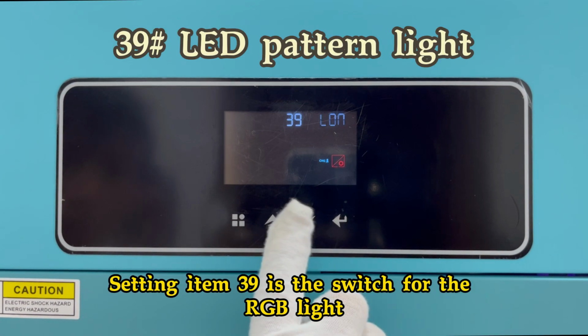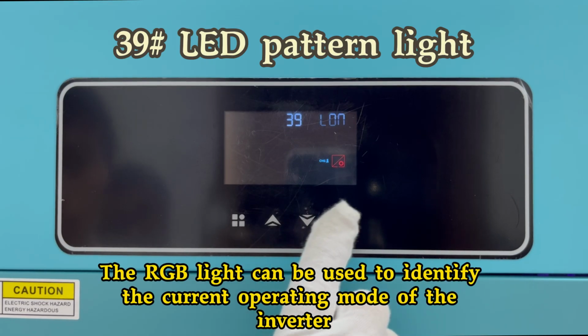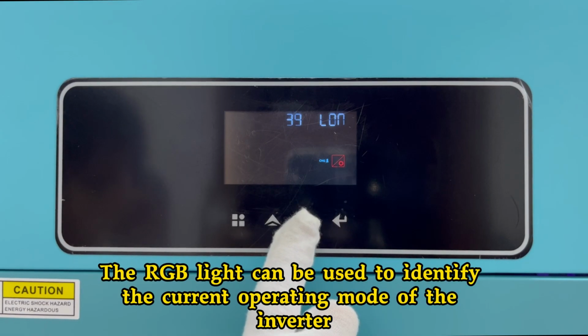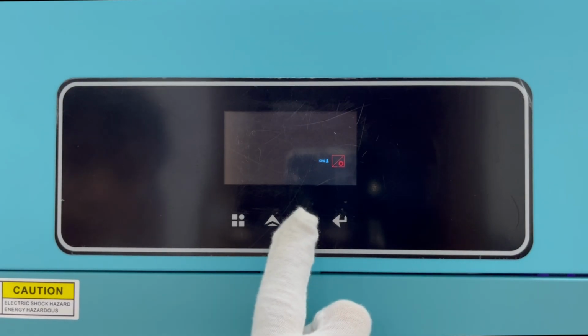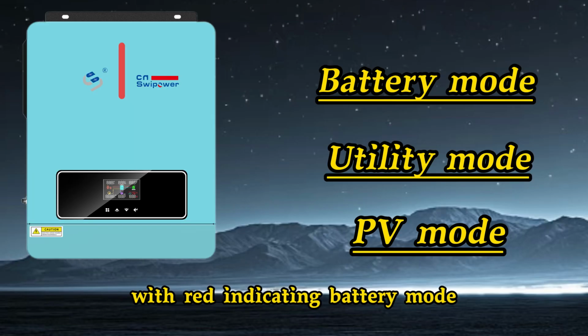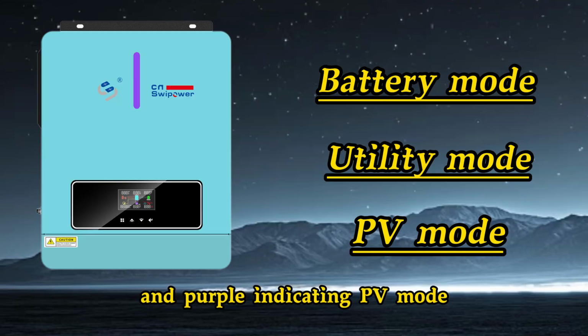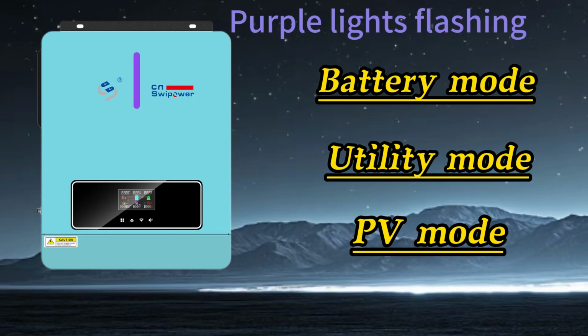Setting item 39 is the switch for the RGB light. The RGB light can be used to identify the current operating mode of the inverter, with red indicating battery mode, blue indicating utility mode, and purple indicating PV mode.